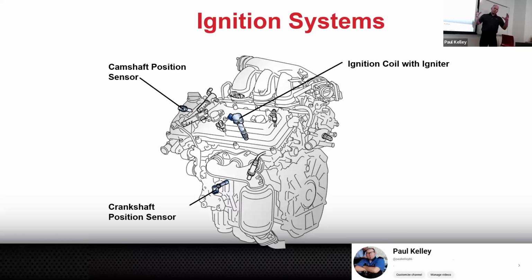So we did the compression and the base engine stuff. If you got a misfire, I'd probably actually start with a spark test because it's easier and faster. But if you pull the spark plug, the coil out, and you hook your spark tester on there and it's got spark, then cool, let's go right for compression because your coil's already out. And if you got compression, then you're kind of stuck with fuel. Fuel's a little tougher to test, but we'll get to that one next unit. But for now, let's focus on it's just a no spark.